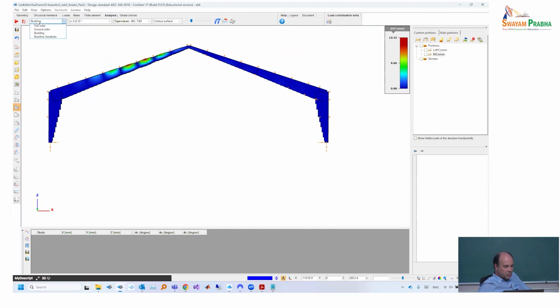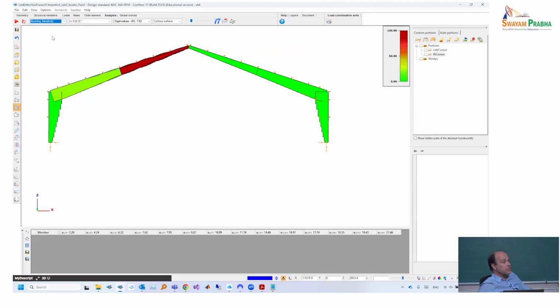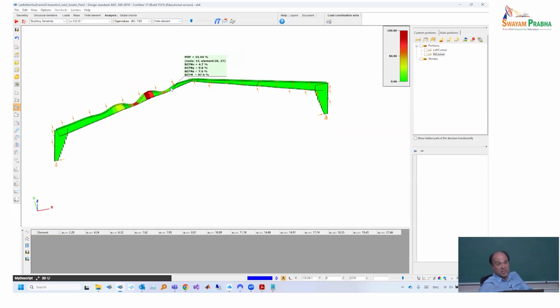Now, how is it done? For this, there is no code regulation or sophisticated calculation. This is an in-house developed, I believe relatively smart approach, which considers every buckling mode as a possible deformation. The eigenvalues are not millimeters, they are just numbers. You can convert them into imperfection by multiplying with a scaling factor to change them into millimeters. You can say, let's multiply them with 1 millimeter, and now they are already deformations.